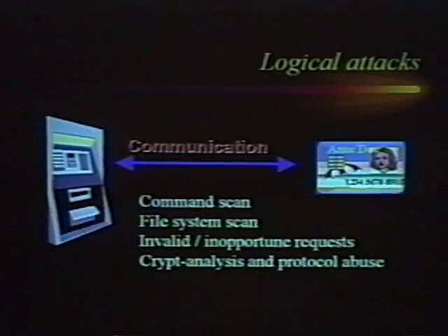So I'll move to another class of attacks, the logical attacks. Although I haven't got too many slides about them, this can be quite an effective and dangerous class of attack. The reason is that we need hardly any equipment. I'd say you just need an ordinary PC and a card reader. What could we do? We could do a command scan. So try to find out all the commands that are supported by the smart cards.